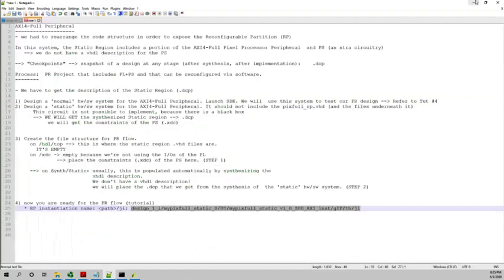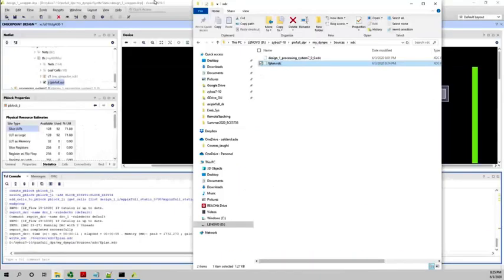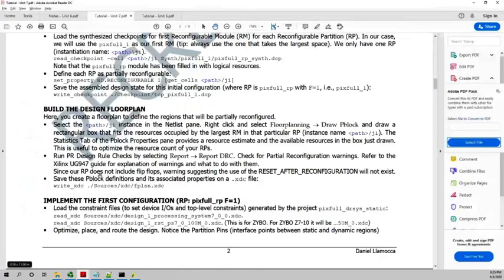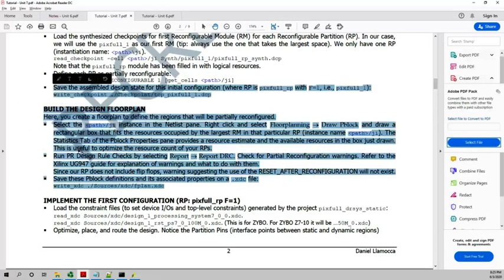By the way, I think the next example that I will show is the DCT. You will see how you only need to complete up to this point, and then you have to do a few modifications, and then you can just run the design complete Tcl and create the bitstreams right away in one single go, okay?